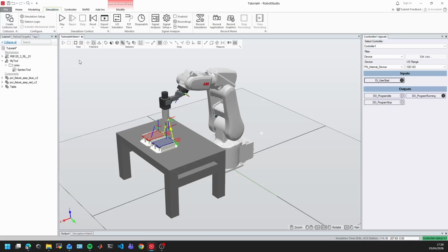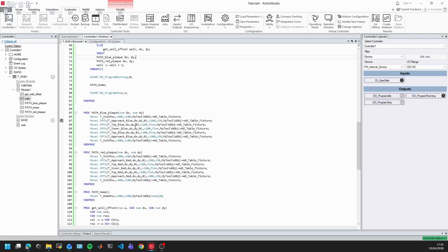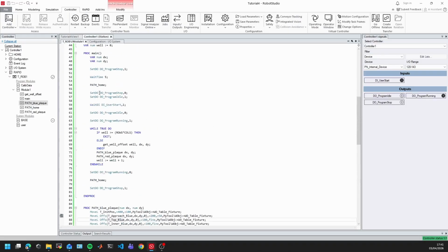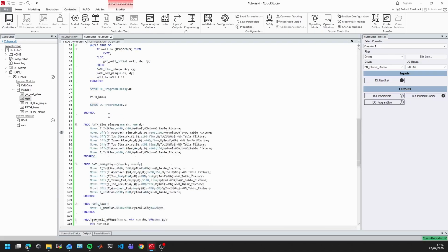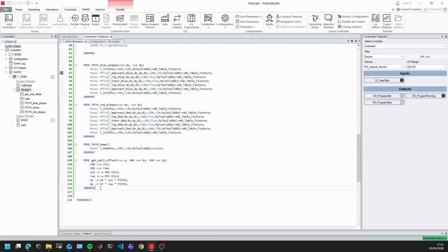I'm going to stop it. A cleaner way to program these set digital output pins, especially if they are for making some announcement like a turret, or maybe turning on some LEDs, is to put them in a subroutine.